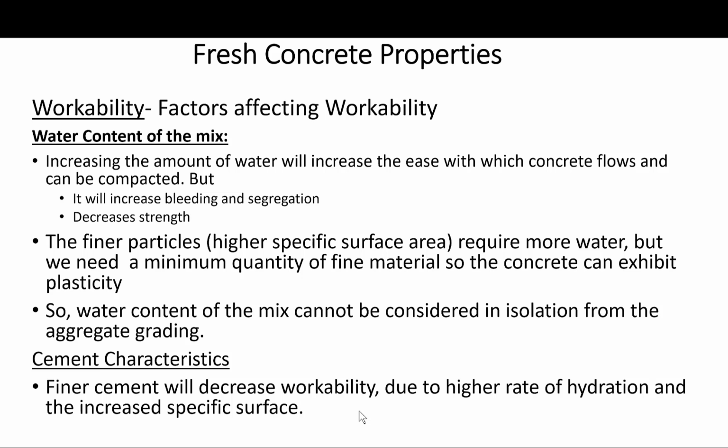On the other hand, without a minimum quantity of fine material, the concrete cannot exhibit any plasticity. So there should be a balance. So the water content of the mix cannot be considered in isolation from the aggregate grading. And you remember when we talked about aggregate, we touched upon this subject. So for optimum workability, finer aggregate grading requires higher water contents. So again, there has to be a compromise and a balance between the fine aggregate content and the water content.